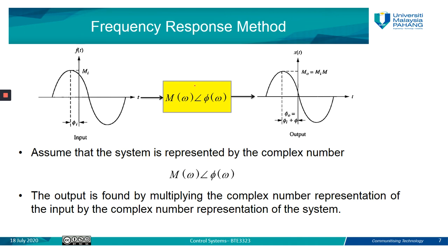We have a block diagram representing the transfer function of the system G(s), or T(s), whether for open loop or closed loop, which consists of magnitude and angle. As we said, G(s) can be represented by magnitude and angle, as we mentioned in chapter 4, when we talked about the magnitude of KG(s)H(s) and the angle of KG(s)H(s), which should be an odd multiple of 180.